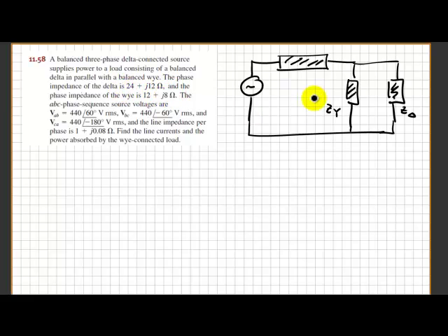So for that delta, you have to convert that into the Y connection. As I say, every time when you put information, no matter what kind of topology, delta Y, Y delta, delta delta, Y to Y, you're going to convert everything into a Y connected configuration. So it's good to have this information written in this way, right?